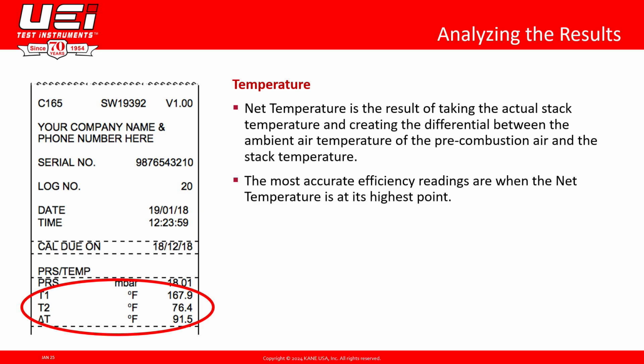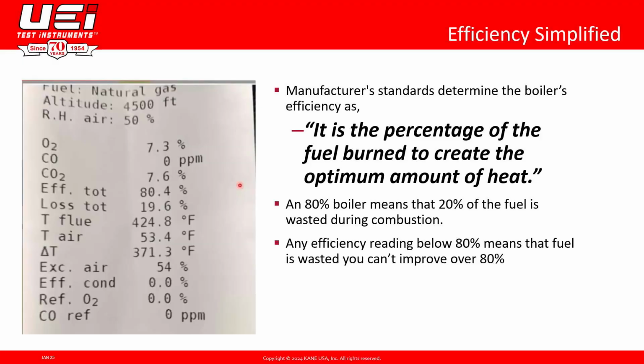Another important factor that we're going to be looking at is temperature. So if we have a stack that is burning too hot or too cool, we're not going to be maximizing the efficiency for our equipment. And I've mentioned efficiency multiple times during this presentation. And I also want to make the distinction, though, when we're talking about combustion efficiency, we are talking about very much a snapshot in time.